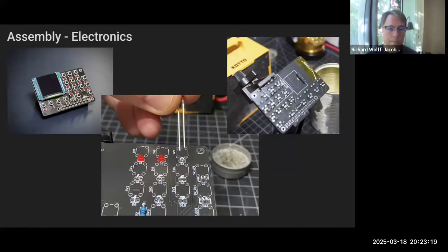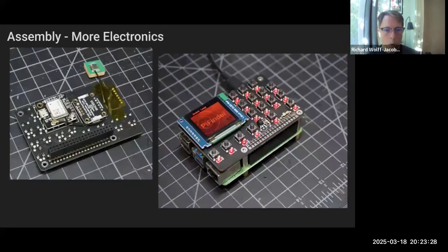So I think if you've done like an electronics kit at all before, this is going to be sort of that same thing and should be pretty approachable. All of the really tricky bits, like the GPS and the accelerometer, are on their own module boards. You buy that board and all you have to do is solder them on to the carrier. Again, pretty easy stuff. And it has a high likelihood of success.